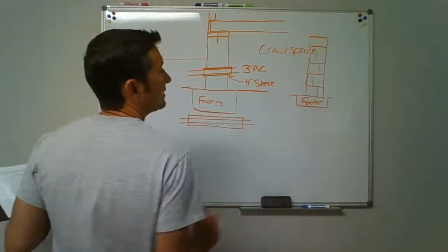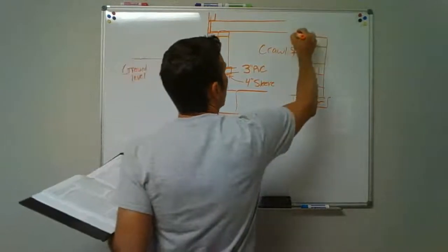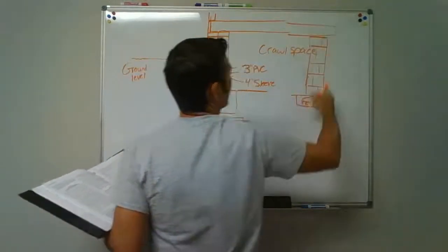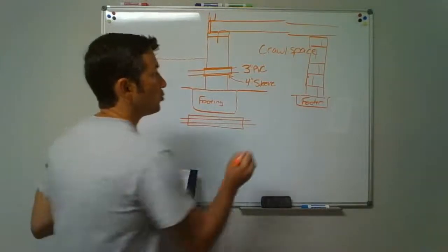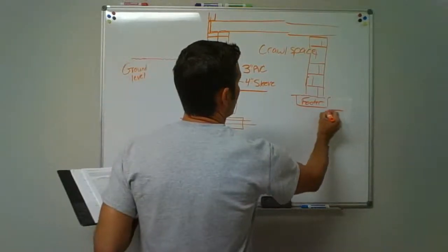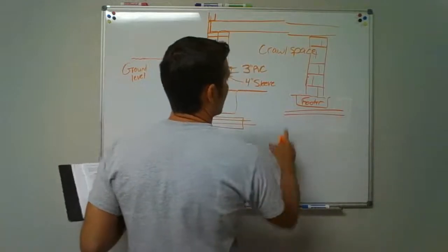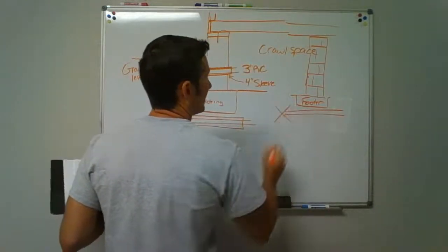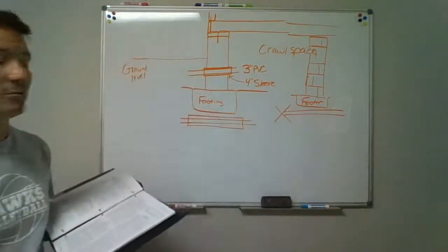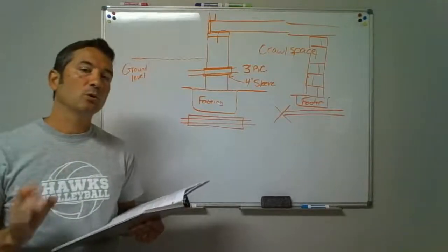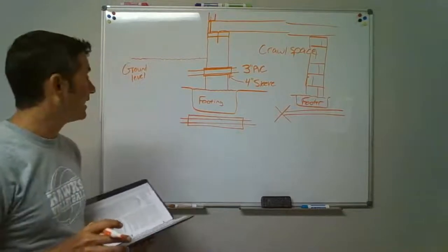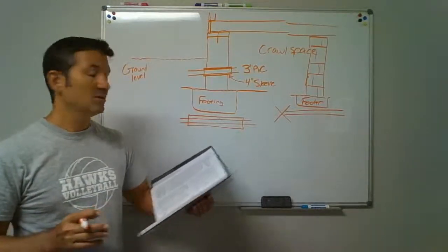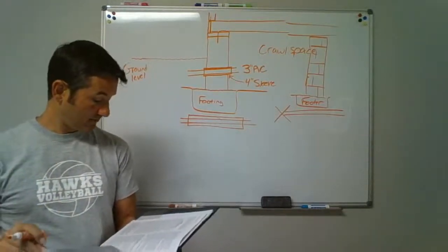Okay, they put some blocking in there, and that's going to have a load on it. They call that a pier. And it says they do not want us to run a pipe, this is not allowed, we're running a pipe underneath the pier footer. So it's really only wanting you to put pipes underneath footers absolutely when you have to, and then sleeving them when required. Okay.